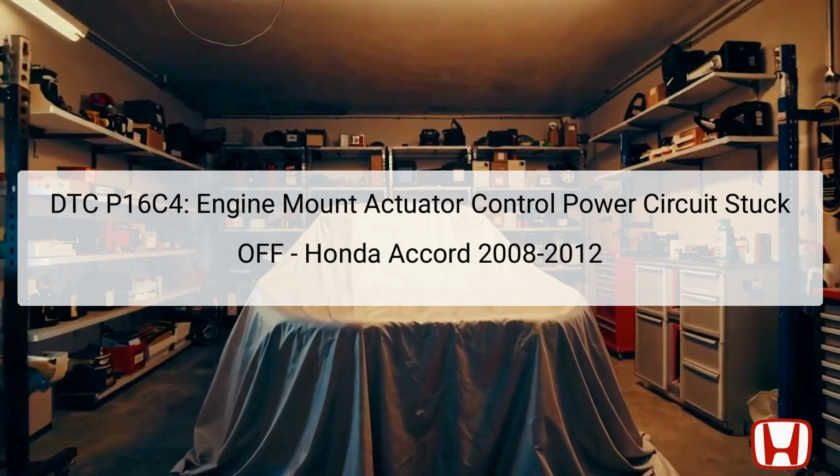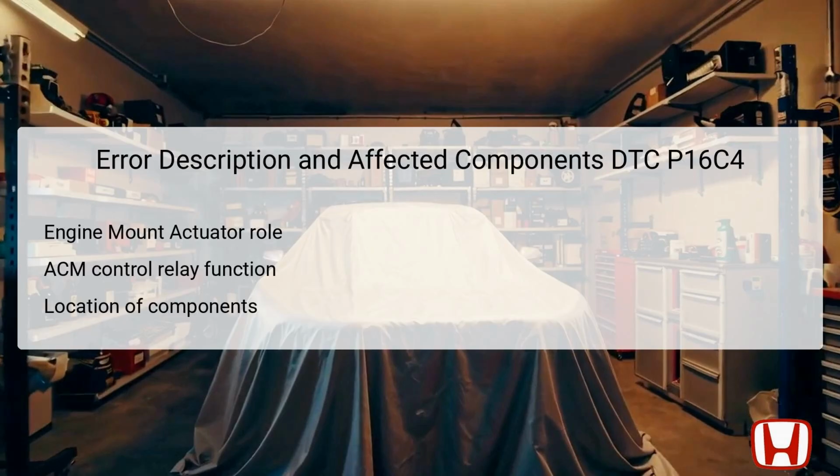the circuit itself. The engine mount actuator's primary function is to manage the engine's position to reduce vibrations that reach the cabin. The active control engine mount, ACM, works by dynamically adjusting the stiffness of the motor mount based on the engine load and RPM settings, creating a more pleasant driving experience.